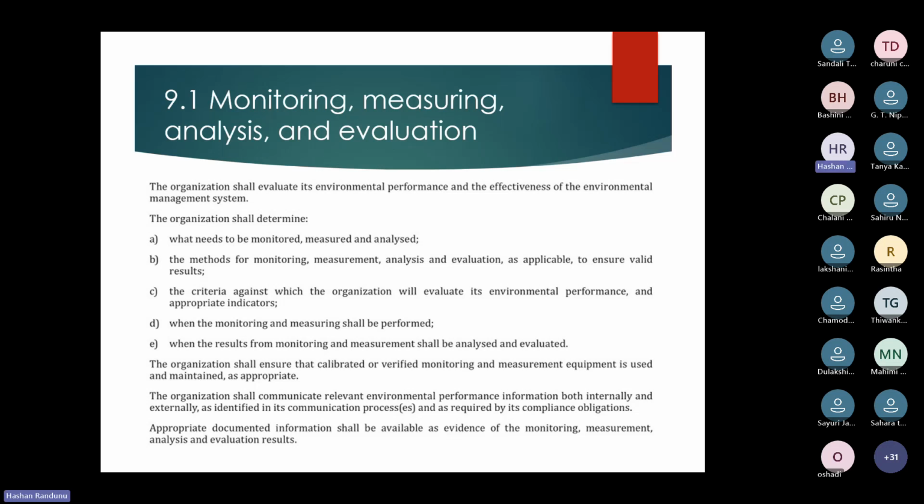Think you have monthly internal treated wastewater reports. Suppose you have those 10 to 12 reports. Then what you can do is identify the trend. You can graphically illustrate the values for the parameters. If a trend is increasing, let's say the BOD value is increasing for the last 2 to 3 months, then there is a possibility for the BOD value to increase further beyond the accepted level.